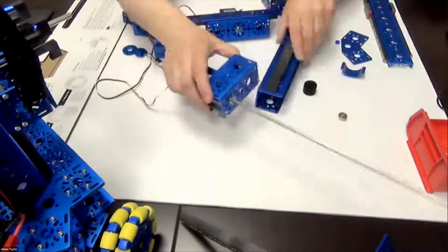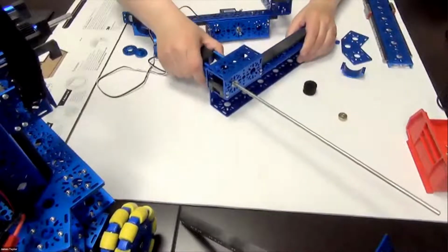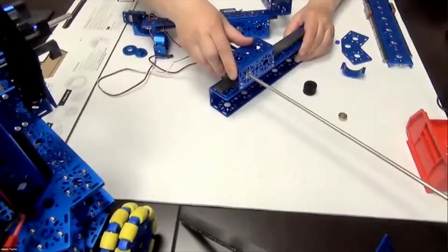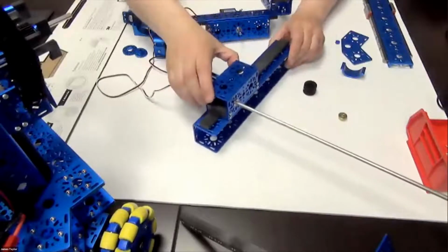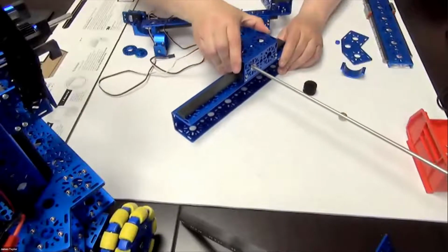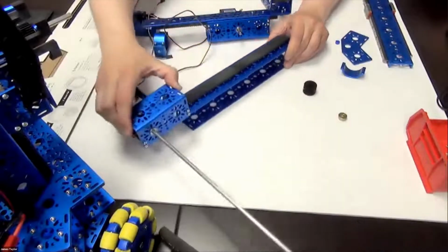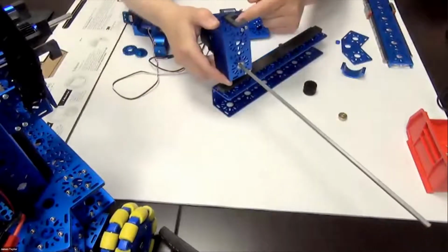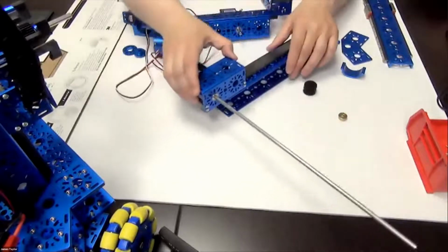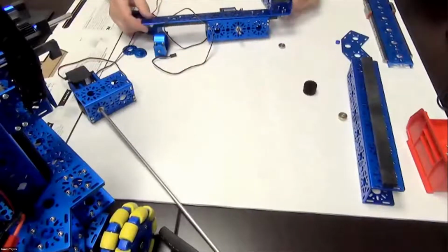And when you mount the whole thing together, all right, and slide it on, right now because the motor is locked, I cannot move it. Okay, but basically as the motor moves, we translate that rotational motion, okay, into linear motion. All right, back and forth. So in this case, we use the two guide brackets. All right, we put them onto the smaller channel, and then the whole thing slides in. So I gave you a picture of that so that you can see it.